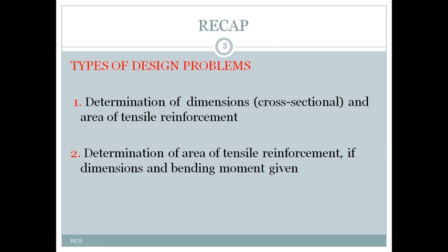That value you have to check with the minimum area of steel and the maximum area of steel we can provide according to the codal provisions. So those are the things we have elaborately explained, and we have designed some problems, some beams also, from the given data. So this is all the story of your beam design. That is, we have designed with respect to the bending moment, considering the limit state of collapse in flexure condition.